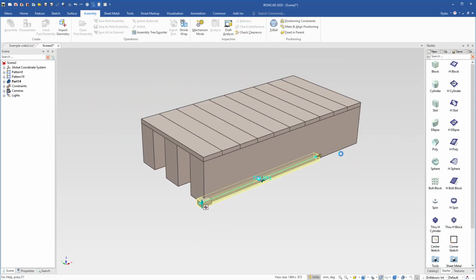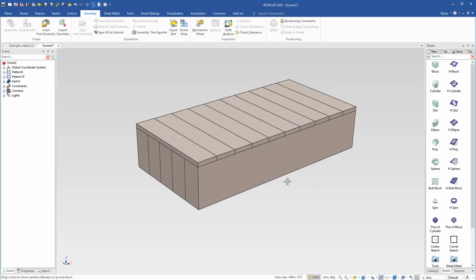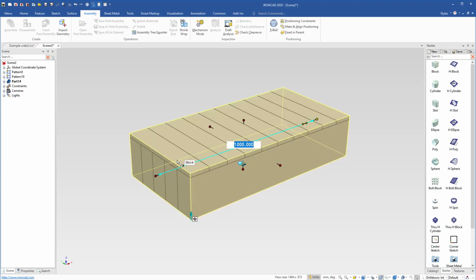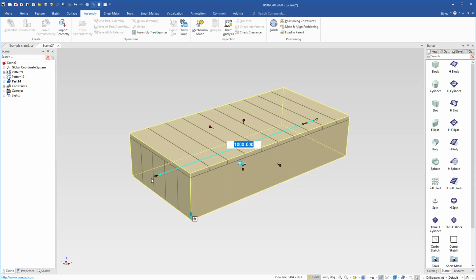And just basically to start off with, I'm just going to size it as the same size as our current assembly here of parts. Pull this out and snap to these locations. And just do our overall height here, snap it. So we basically got the overall size of that thing. The reason we're using that block is that's what we're going to use to set the assembly handles to be parametric. As I mentioned before, these objects that got parametrically controlled changed their colors when we did that. We want the same thing to happen on this block. We want these length and width handles to be parametrically controlled. And we don't really care about the height. We're not going to change that in this example.